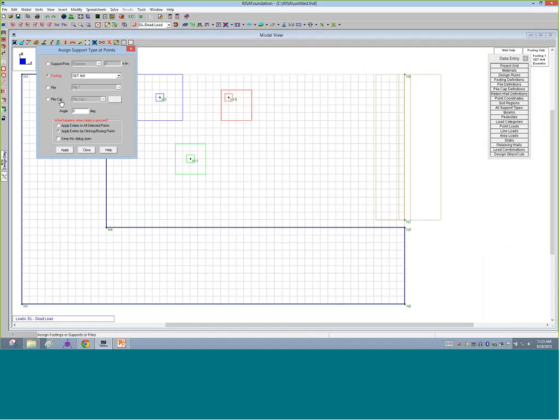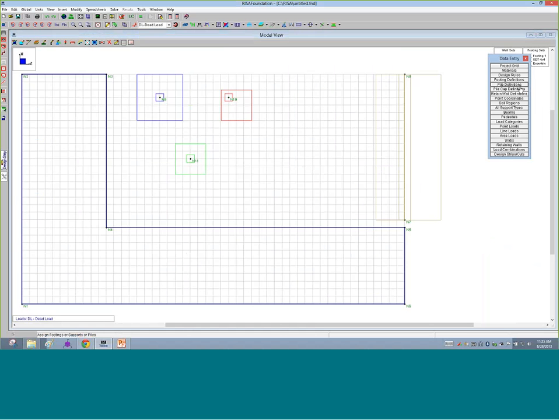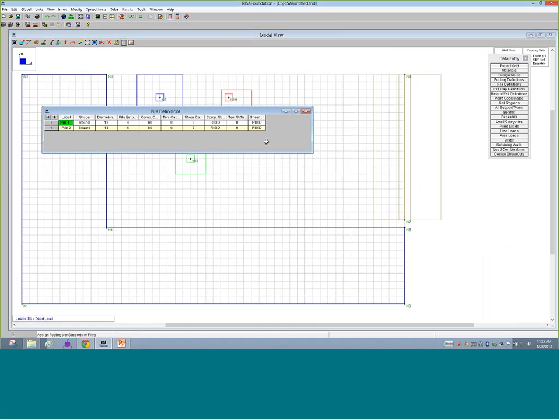What I'm going to do next is talk a little bit about piles. So piles, there's two types of things when we talk about piles themselves and pile caps. So let's see, with piles, we have two types of piles available in our default settings, and let's take a look at what a pile is. So if we close this up and I open up my pile definitions, really, what are piles? Piles are used when you have soil conditions where you need a little bit extra depth and you're trying to use a pile to help support your slab or footing or pile cap, for example, which is very close to what you'd think of if you think of a footing.